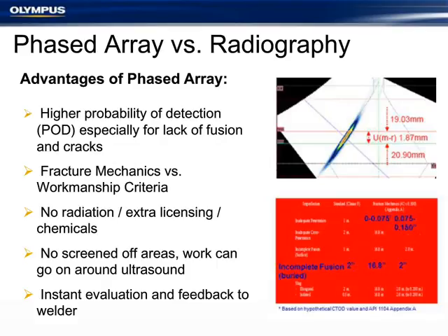Also instant evaluation. If we do a scan with ultrasound, the analysis data is immediately available, and especially welds that have no defects, a qualified operator can make that call very quickly. If we do a repair, we can immediately put a manual phased array probe on it and tell if that repair was good. So we have really instant evaluation and feedback provided.